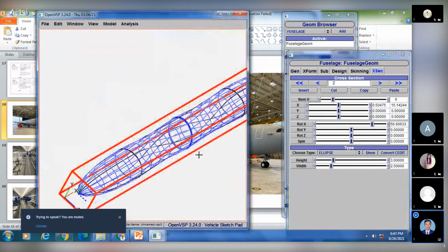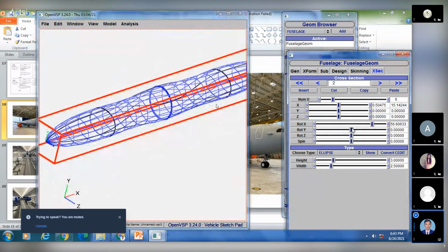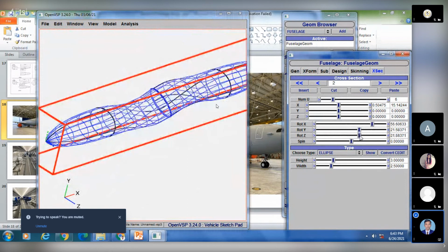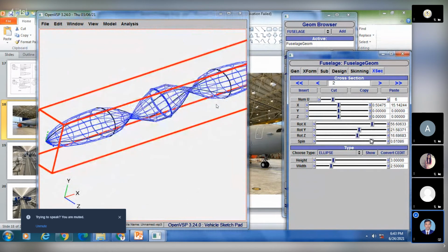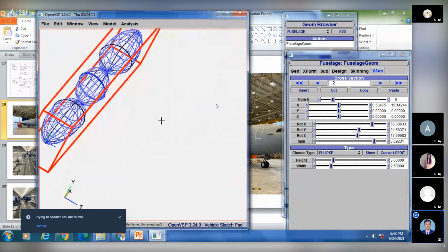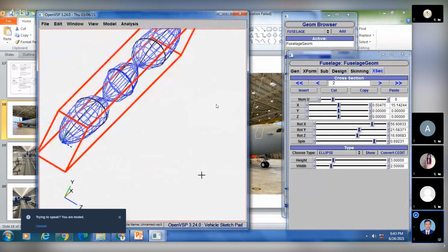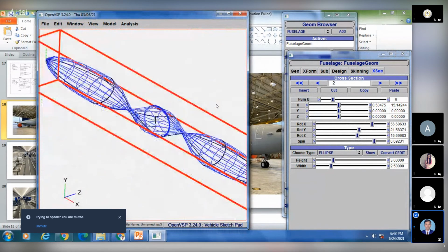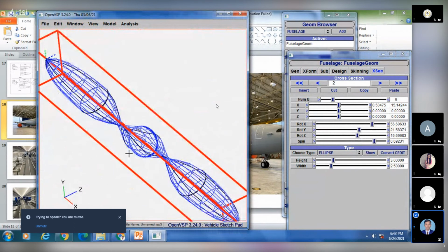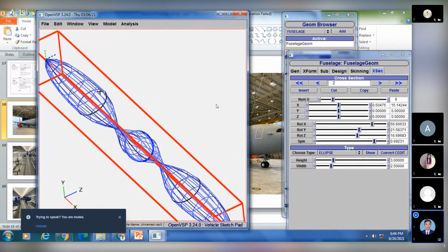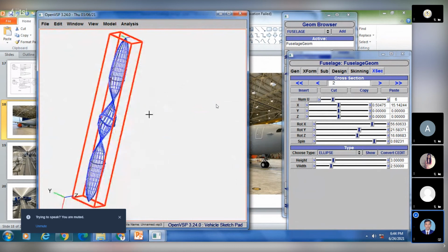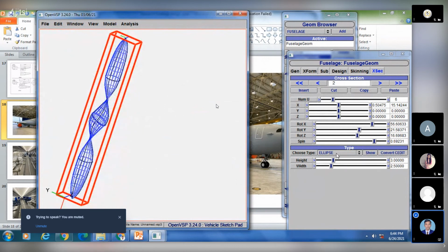Like this, you can even rotate your cross section along x, along y, along z, and also you can spin. See, I don't need this geometry, but automatically I got that one. So any kind of geometry can be designed once you know the parameters, and once you get the proper idea of how to add them in OpenVSP as an input and how to get your particular geometry as an output. If you know only that, you can easily get the model you are looking to design. Now, as I told, you can have a preview for each and every cross section.